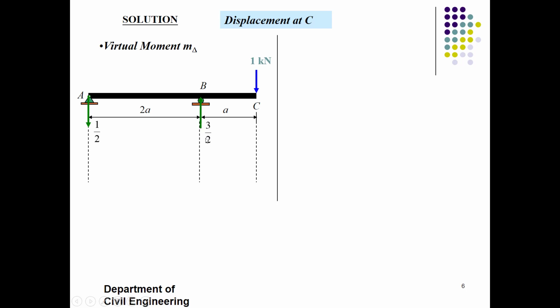Alternatively, you can also calculate the reactions by converting this unit load into a moment value, which would be 1a, 1 multiplied by this overhang portion, and 1a would be applied at B in the clockwise direction. For example, 1a is your answer for the moment resolution.